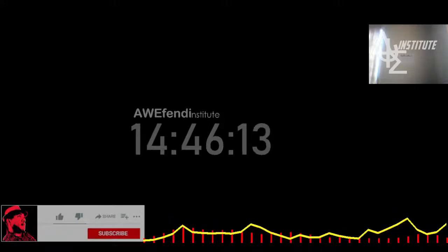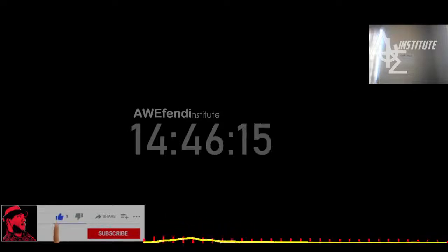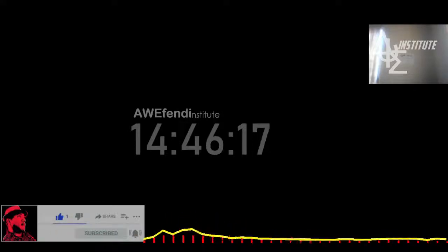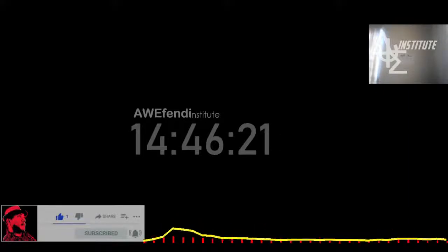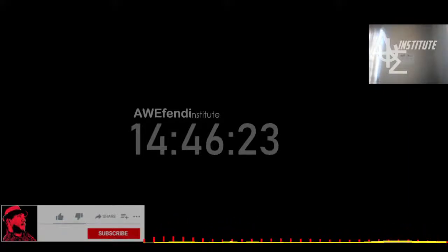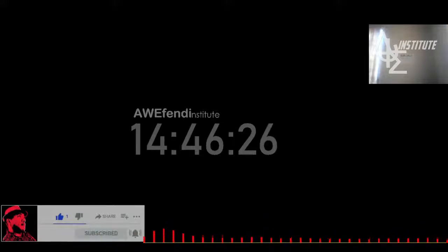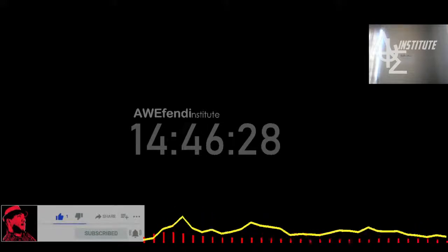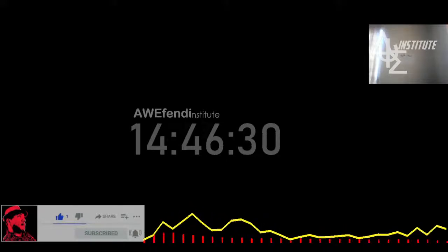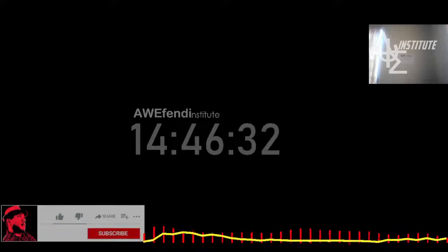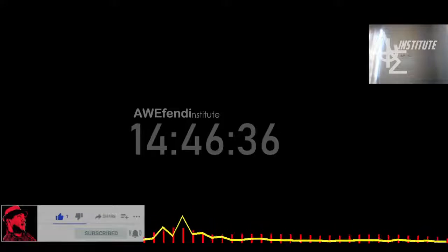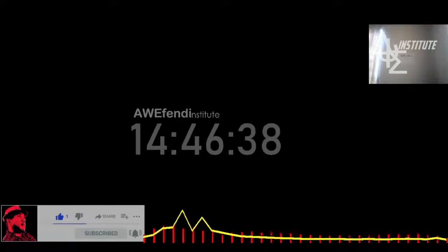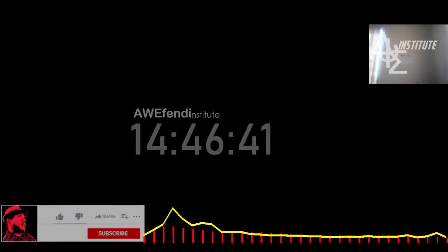Another thing that we wanted to check is the directionality of the heat flow. And for this, we can actually plot the heat flux vectors. And we can maybe make them a bit bigger to see what we're looking at. And we can see that the directionality is maintained. Again, this can be pretty obvious if you have this kind of geometry, but if you have a complex geometry with different heat sources, even verifying which direction heat is flowing might actually not be trivial.